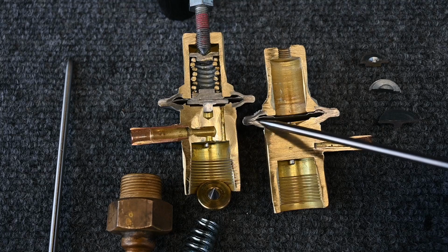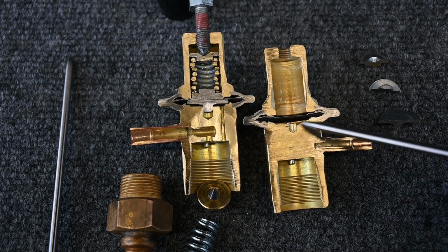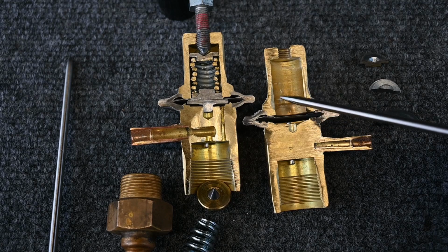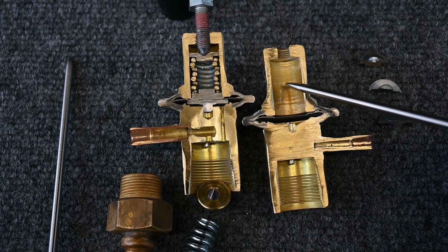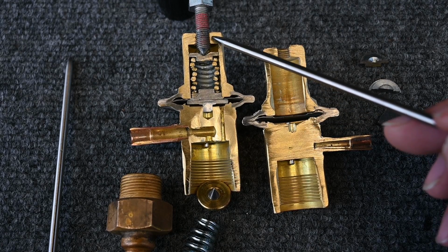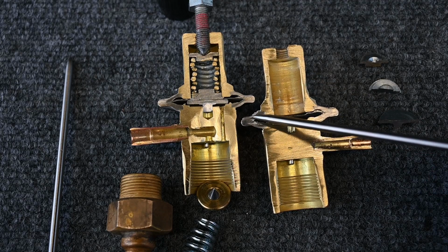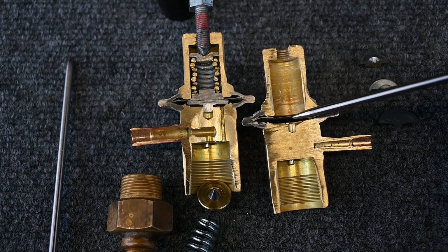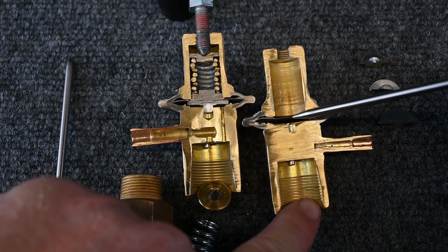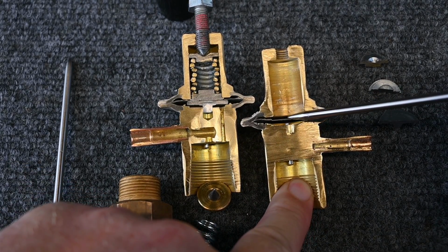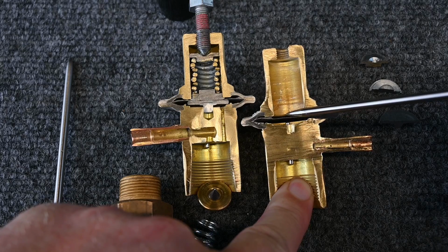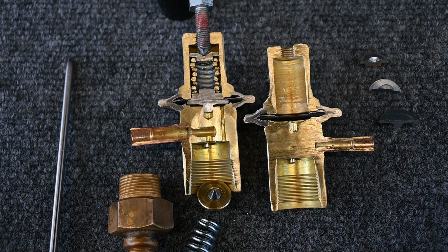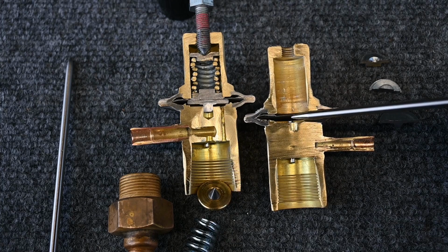By having this thin piece of metal here, welded all the way around, it keeps the suction all on this side. In other words, it keeps that suction pressure from entering this top part of the valve, because there wouldn't be much keeping it from leaking out of the threads here. So this plate being sealed keeps the refrigerant held in. Also, this plate being thin allows it to move. So this plate moving is very important, but it has to be thin enough to allow it to move.